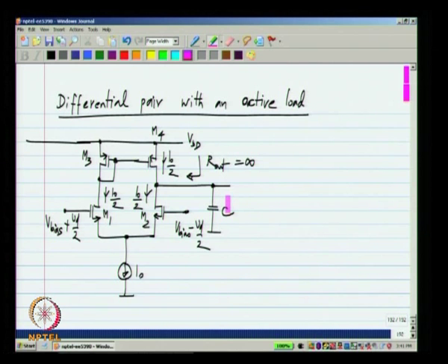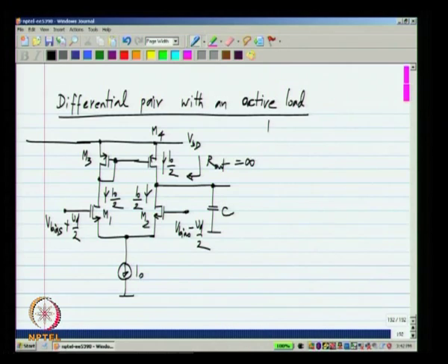And that will be the ideal case when we have a transconductance with infinite output resistance and the op amp behaves like an ideal integrator. In reality, the transistors will have some GDS, and we have to analyze the effect of that we are going to do soon. Okay. But this is a topology that can be used, because it gives a very high output resistance, as high as the value of GDS can possibly be, and it converts the input difference voltage into a current and drives it out. Okay.